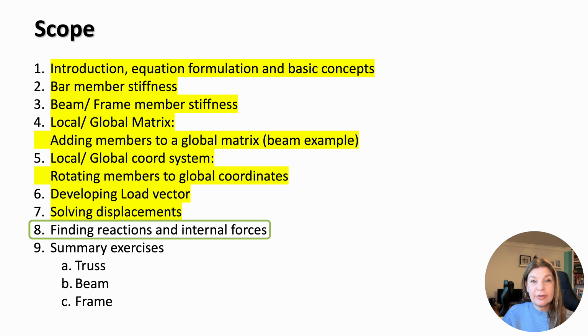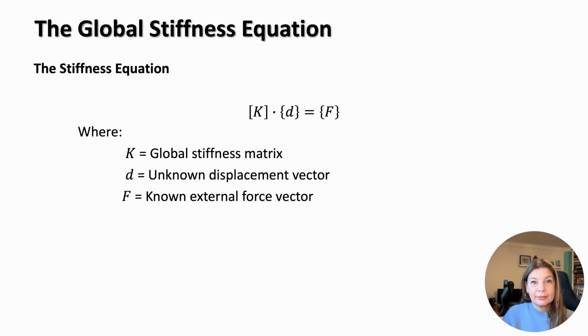to coding. So far, we've used the stiffness method to build and solve the equation KD equals F, giving us the displacements of every node in the structure. We've also calculated support reactions and internal forces carried by each element in a truss. We will now move on to completing exactly the same procedure, but in a frame. We'll recap and discuss the theory, we'll solve an example, and then we'll move on to programming the whole process.